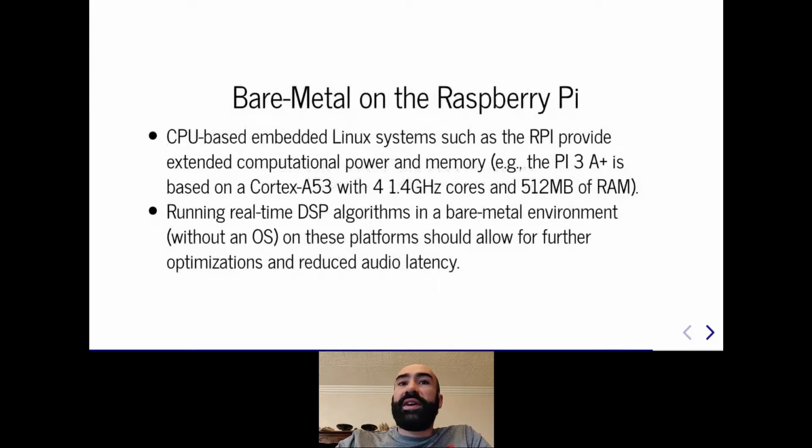Generated objects consist of kernels that can be placed on the Pi's SD card. MIDI and polyphony support has been implemented as well. The current toolchain remains relatively cumbersome, unfortunately, and that's mostly because of the use of the SD card, which has to be taken off the Raspberry Pi every time a new program is created. The system is currently completely static, unfortunately. Furthermore, the Raspberry Pi doesn't give access to proper audio inputs and outputs, and to sensor inputs, except through a microcontroller, making it unusable in the context of embedded musical instrument design.